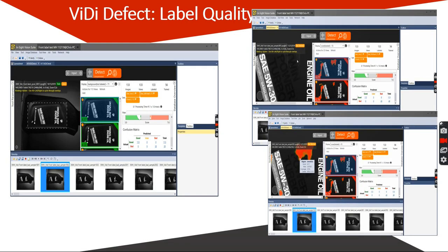Moving on, here's another application where we've found a lot of success applying ViDi to the quality of labels, to make sure that the right label is on the right container, and in the right position, and that it doesn't have, as you can see in the very top image where my cursor's at, any kind of wrinkles or blisters or tears or scratches anywhere in the label. To program that with rules-based vision is difficult. It takes a lot of time, and you can really only find gross defects.